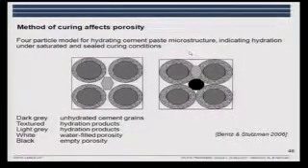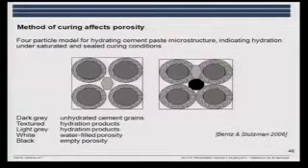They measured it differently. They measured with a technique, low temperature calorimetry, or differential temperature scanning, where you freeze the sample and then you monitor when freezing starts. And what they saw was that initially, or after some hydration, for systems which were seal cured, they had a finer porosity.